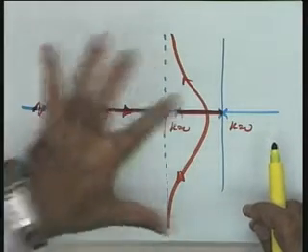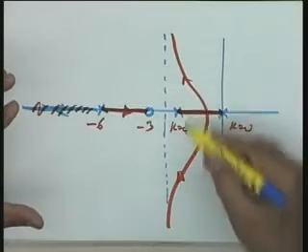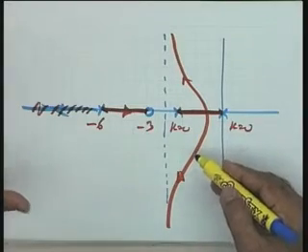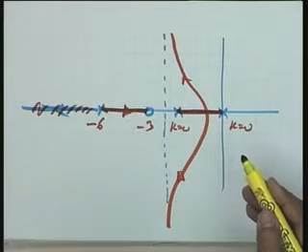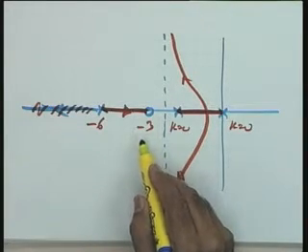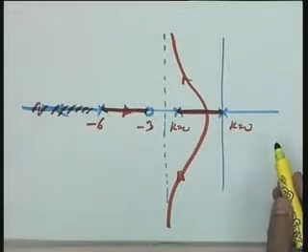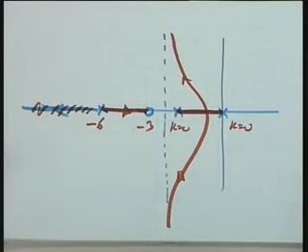You see, actually these plots are nothing but the complex conjugate poles, the dominant poles over here, and these are the closed loop poles. The closed loop poles are going to guide the dynamics of the closed loop system. So once you place your 0 at this particular point, you find that the total plot has been pulled this way, and hence it is a tremendous stabilizing effect on the system.